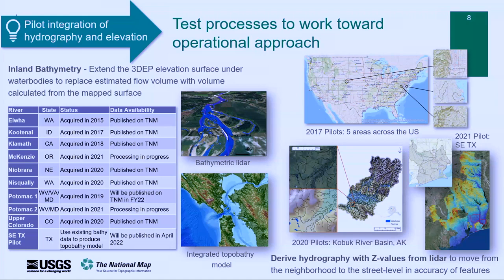So now I'm going to move on to the second development track, which is the actual piloting of this integration of elevation and hydrography together. On the left-hand side, you'll see some of the piloted areas that we have done on inland bathymetry. So we've been working on collecting both topobathy LiDAR as well as integrating in acoustic sonar data to get us this continuous three-dimensional surface above and below the water.